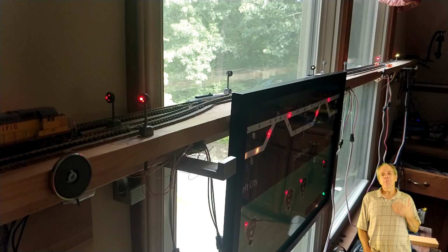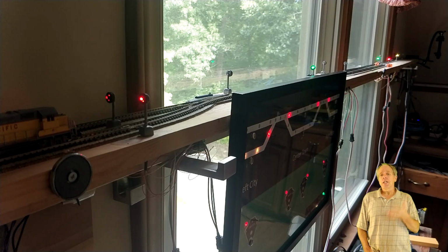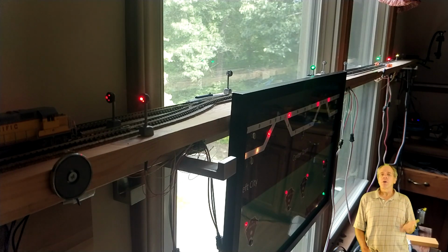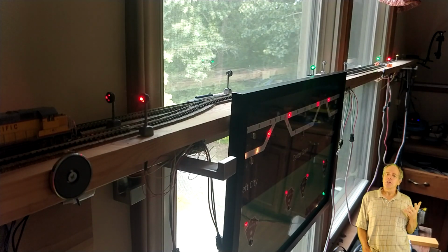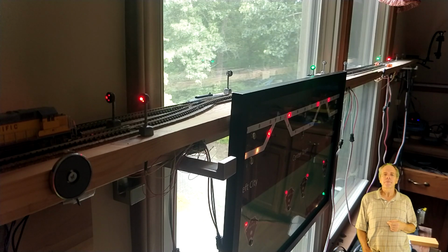I now change the position of turnout 1 from thrown to closed, which causes signal 808 to change from stop to track speed, and as a result signal 804 is changing to track speed as well. Signal 806 on the other hand changes to stop as the track temporarily became a dead end.